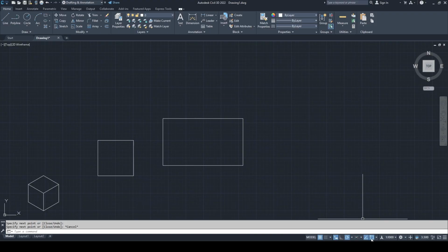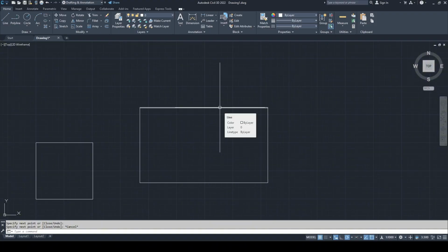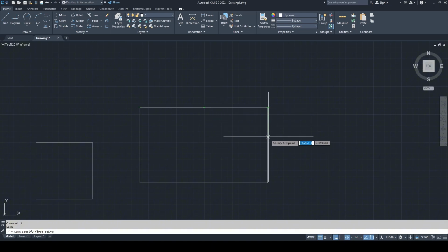The next one is 2D reference points. So upon clicking the object, you can see there are these small blocks, or if I use the line command, you see there is midpoint. This is called the nearest icon. This is the end point, and all these different icons. You can only access these when this command is turned on. So when it's turned off, we cannot access any of these icons.